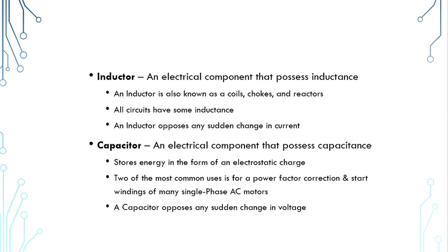Of course, those 5 time constants we were talking about happen really quick. Now, you do have to watch out for an inductive kick. If you had a large wire a mile or so long and you removed the power on it, and somebody at the other end goes to grab it, it would induce that voltage back and put them on the ground. And we call that inductive kick.